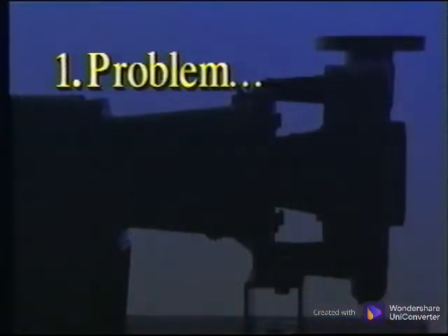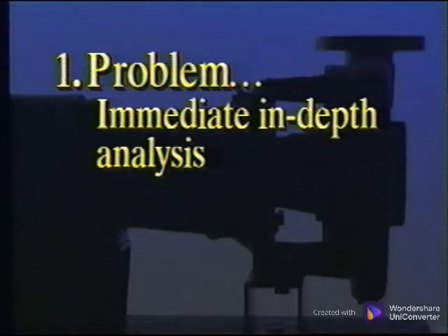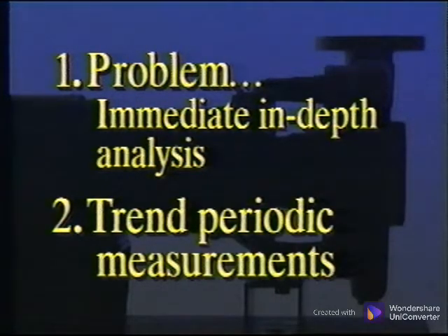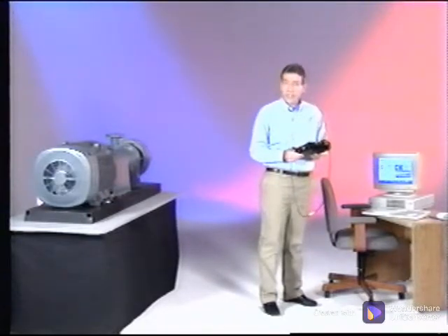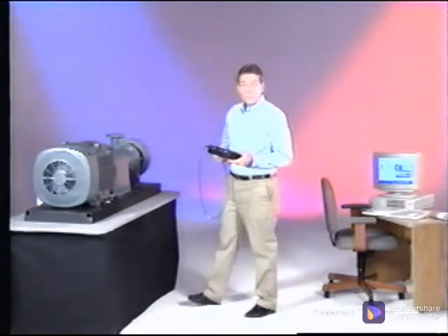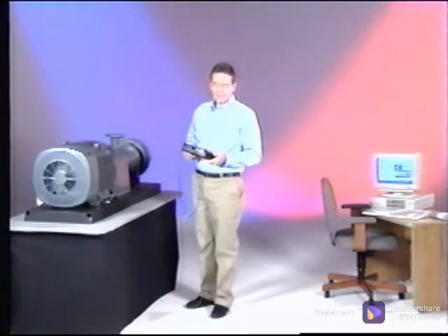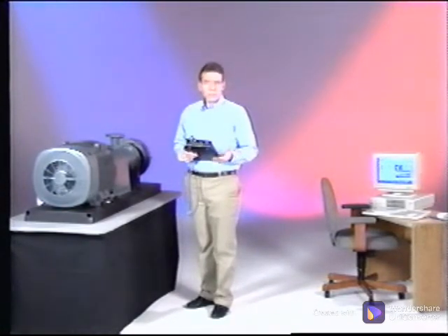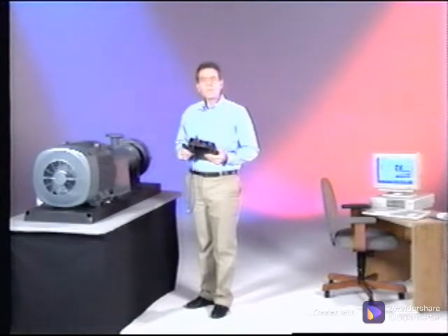There are two concepts for monitoring equipment like this. The first is, only collect data when a problem is suspected, and at that time do an in-depth immediate analysis. The second concept is, monitor the machine on a periodic basis and trend the data for any change that would indicate a developing problem. Analyzing a machine only after a problem has been detected seems to be a logical labor-saving concept. The drawback to this is, we may never know there is a problem until a failure is imminent or has already occurred.